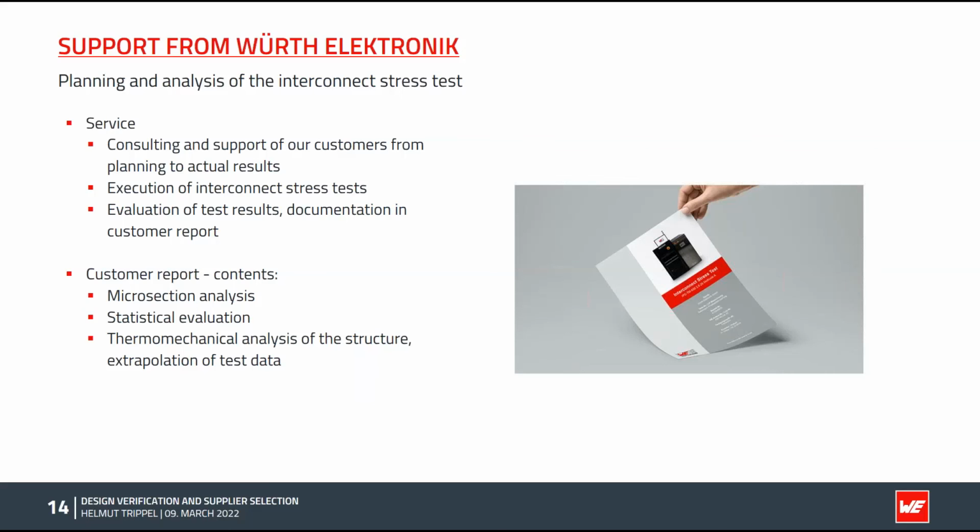We also execute the interconnect stress test in-house. We have about 4 IST machines for testing, and we also do an evaluation of test results and document this in a customer report. As I stated, a customer report or evaluation is a microsection analysis of different failures, a statistical evaluation of the overall failures, and on top of that, a thermomechanical analysis of the structure with an extrapolation of test data. So you are also able to read out from high test temperatures to lower application temperatures.